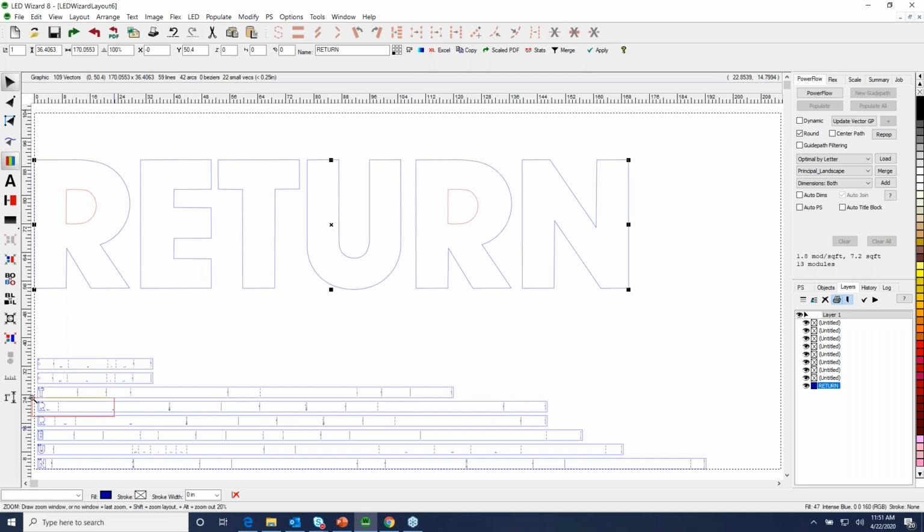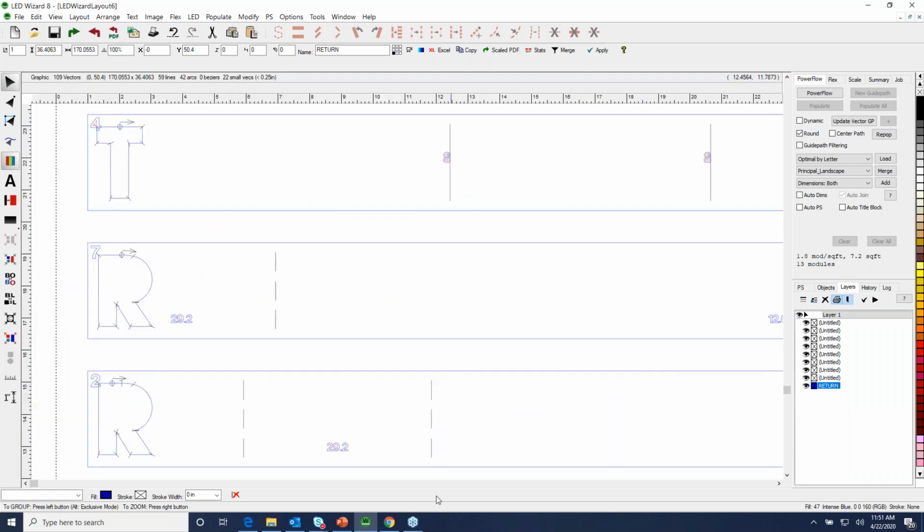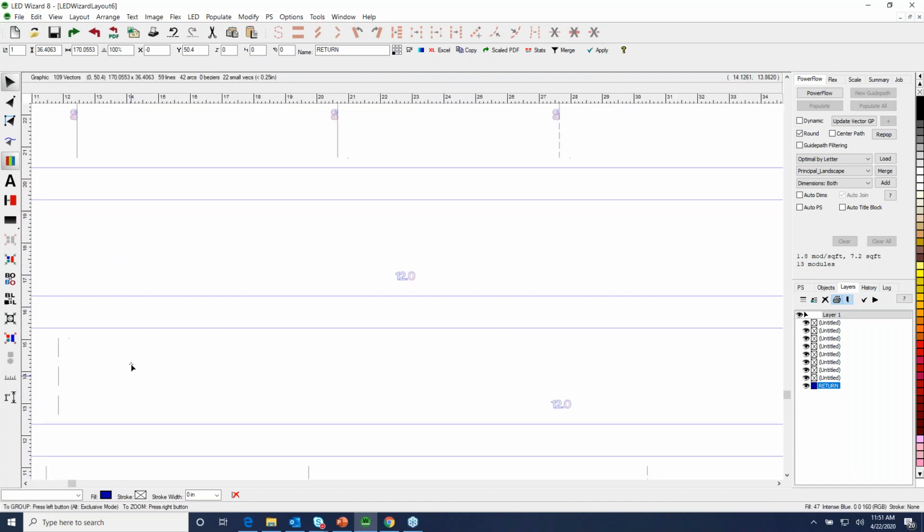Jeff: What happens if you don't enter the tool diameter? Will it do a hard corner with no radius? Correct, that's correct. If you have a laser, or I don't know if a plasma or a water jet can be that precise, I think it is, you can put 0 for the tool diameter. Yeah, exactly.